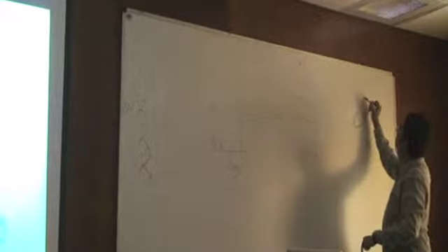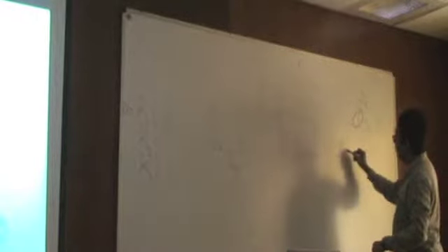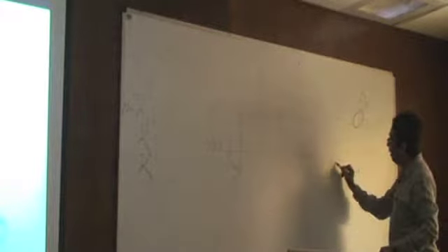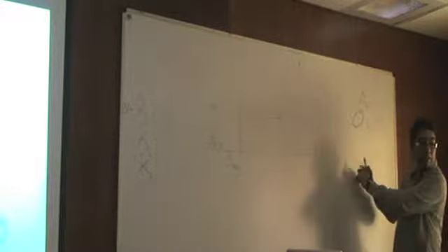When it is bending, if you look at this particular cross section, let's say this is the x2 direction, this is the x3 direction, x1 being along the length of the shaft. What is happening is that the cross section is changing into something like this. It is flattening. The extreme of course is when it forms a kink.